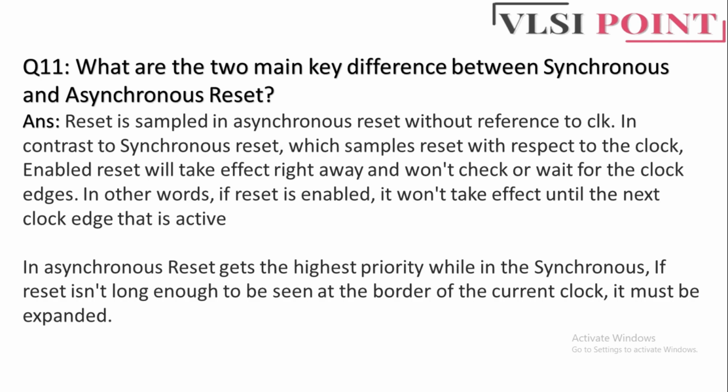However, it requires careful attention to the timing and the potential glitches that can occur due to the lack of synchronization. So overall, the choice of what you should use, synchronous or asynchronous reset, also depends on the circuit requirement too. I hope this theory concept is clear to you.